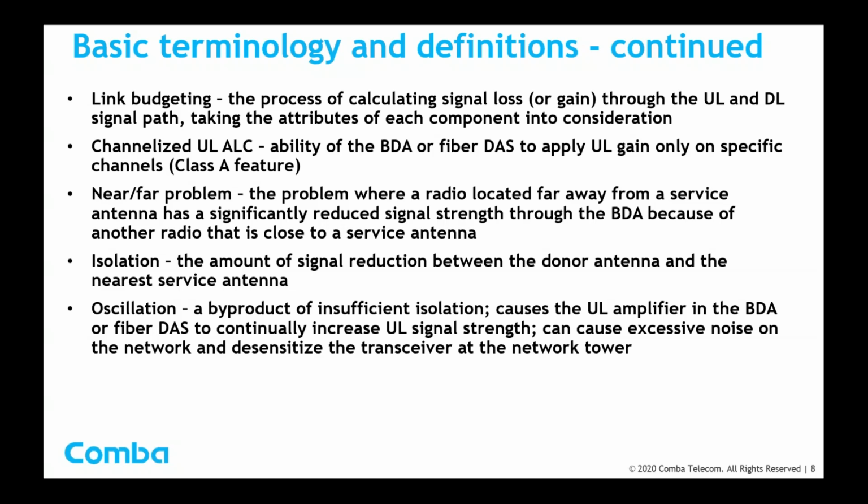Channelized uplink ALC, automatic level control. Automatic level control is the ability of the BDA or the fiber DAS to apply uplink gain. And in the Class A case, it's the ability to do that on an individual channel basis. And again, we'll go through that.